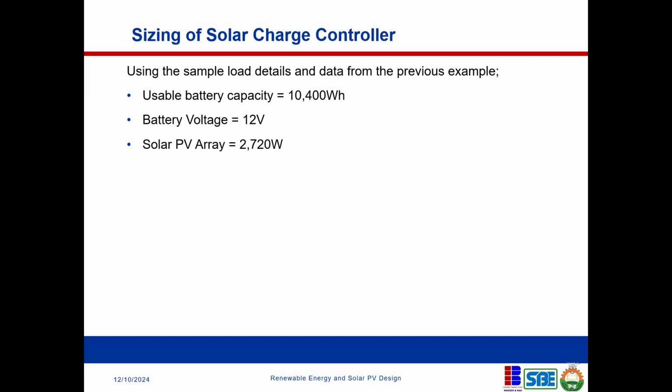Now some inverters have an inbuilt charge controller. So when you're looking at an inverter, please look out for this. Look at the specifications, and that will tell you the capacity of the solar panel you can feed into that inverter. You don't go beyond that, otherwise you also damage your system. To allow some flexibility, you might have a separate charge controller so you can scale up and scale down your panels. That's what the guy recommended, an additional charge controller, which I got until we improve the performance. Exactly. If you have an inbuilt charge controller in the inverter, it already limits the capacity of the solar panel you can feed into that inverter.